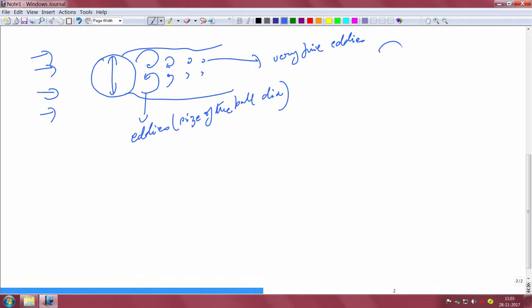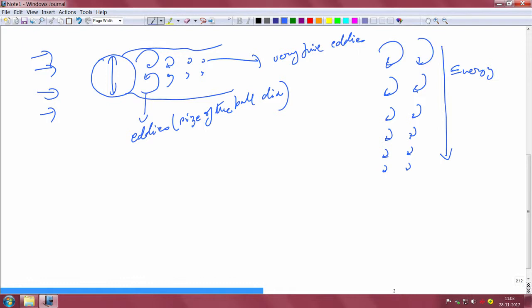So, what happens is that if you look at the large eddies, then you get slightly smaller eddies, then even smaller eddies, then smaller eddies, and then you get to this particular point. Energy is transferred in this direction. So, the large eddies transfer the energy to the immediately slightly smaller eddies, that gets transferred to yet smaller eddies, and this way it goes down to the smallest eddies possible, where they are basically dissipated by viscosity.